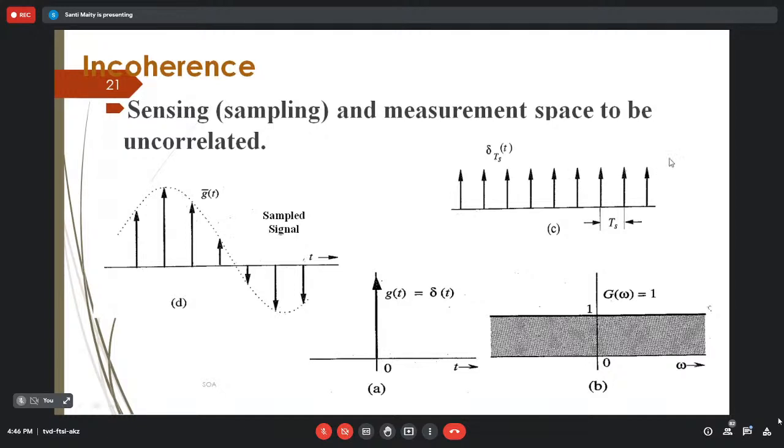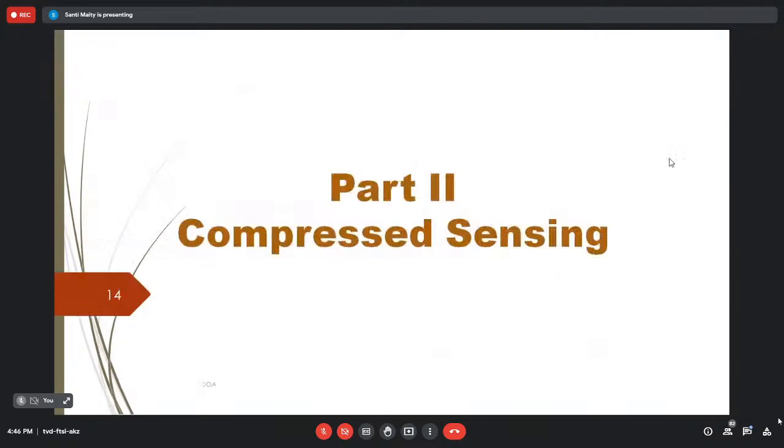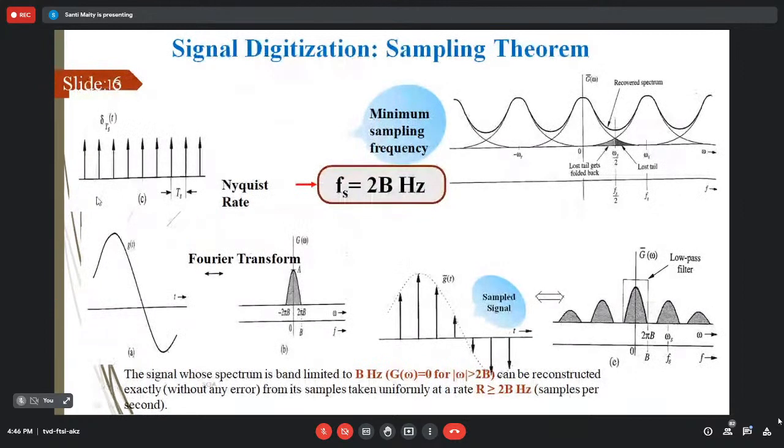So, series of impulses, and I'm coming back to my old slide. So if impulse, rectangular, train of impulses, when multiplied with this gives a discrete time signal. We have to have a certain condition on this interval. Once I say interval, in other words I would like to say sampling interval means sampling rate, means number of samples to be taken per second.